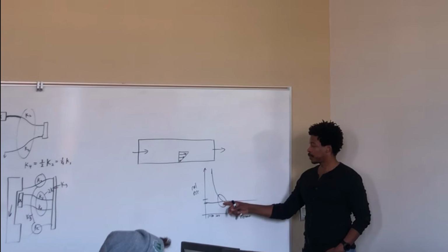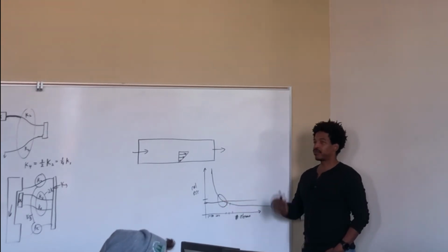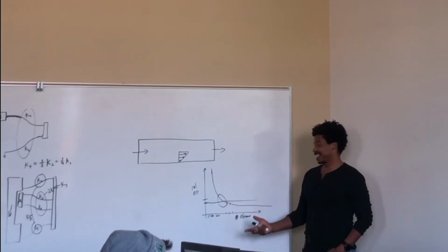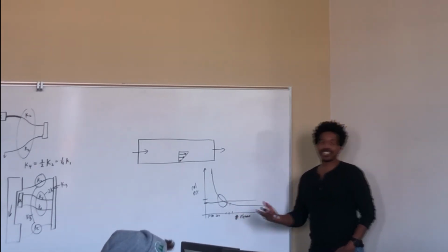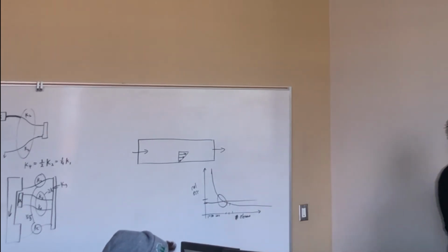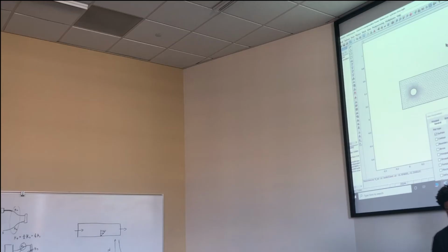I've asked COMSOL people, and typically they just refine the mesh to a finer mesh to see if anything changes. If it doesn't change, then they've reached past the convergence knee. So maybe in the future, some kind of algorithm can be done to deal with that.